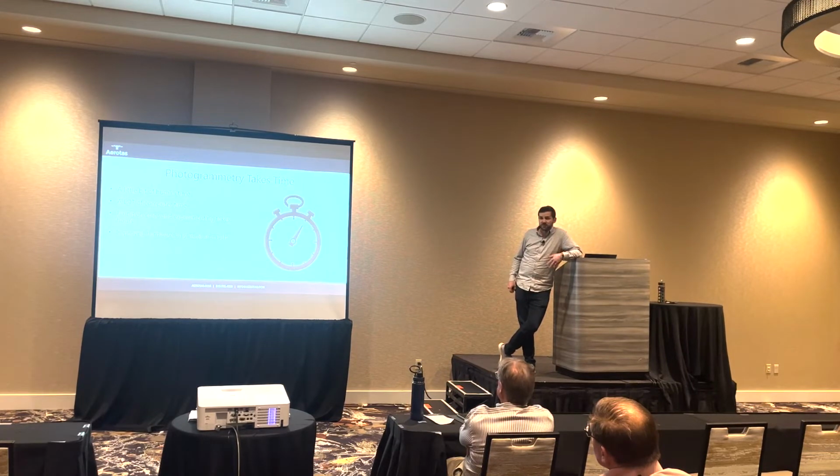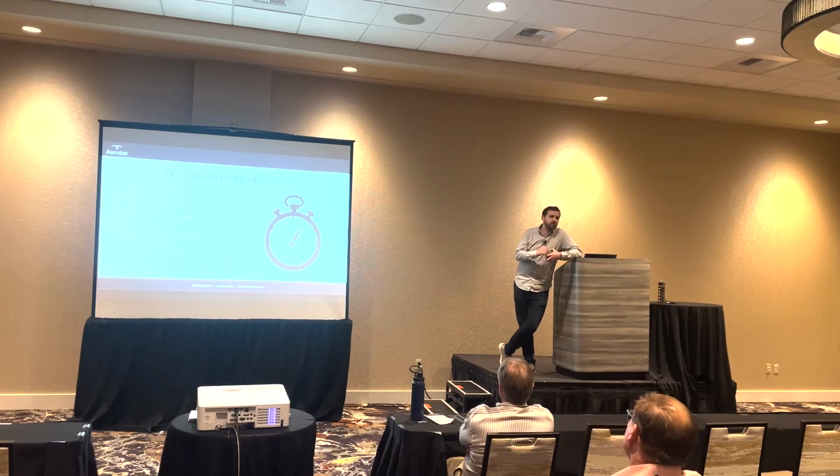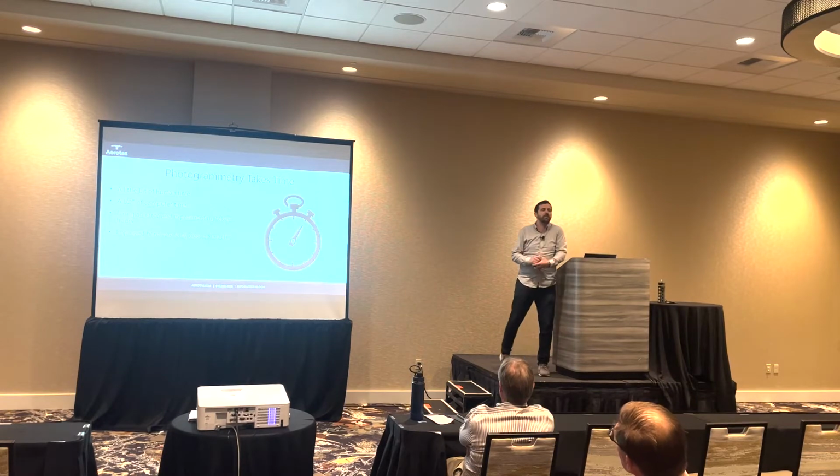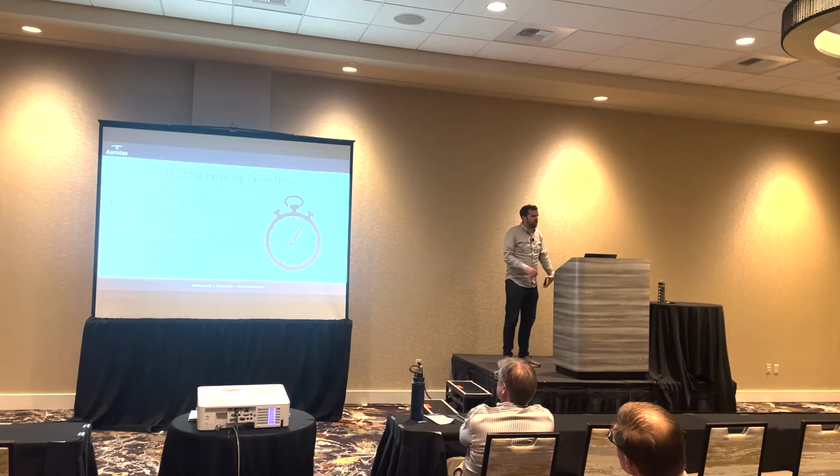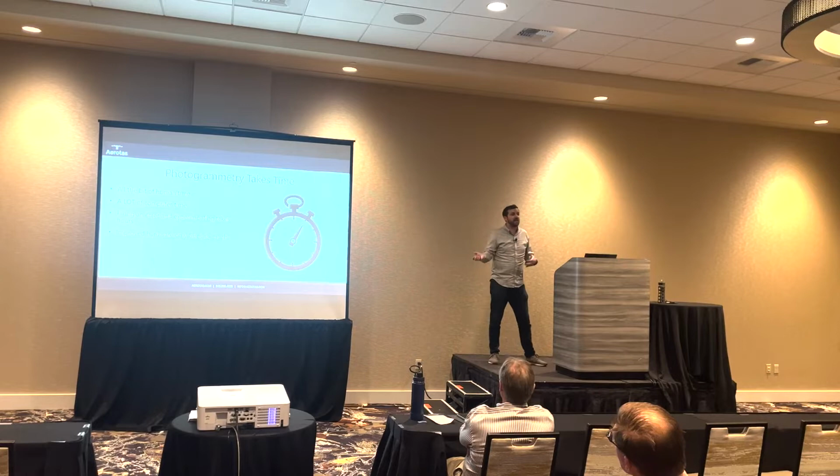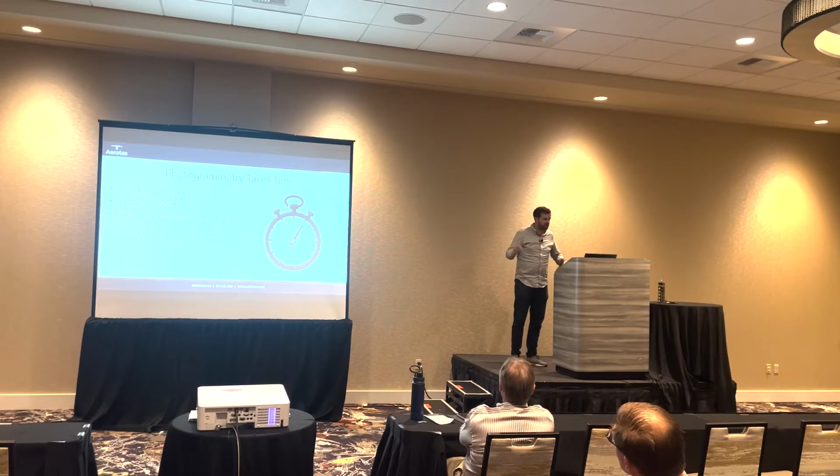For anyone that's done this before using Pix4D, even on a $5,000 computer, your larger projects can take 8 hours or longer if you're throwing a couple thousand photos at it. And that means that fixing an error and experimenting can actually take hours because you might try one setting and then you process it, you come back the next day and everything's broken. And improved hardware only does so much.